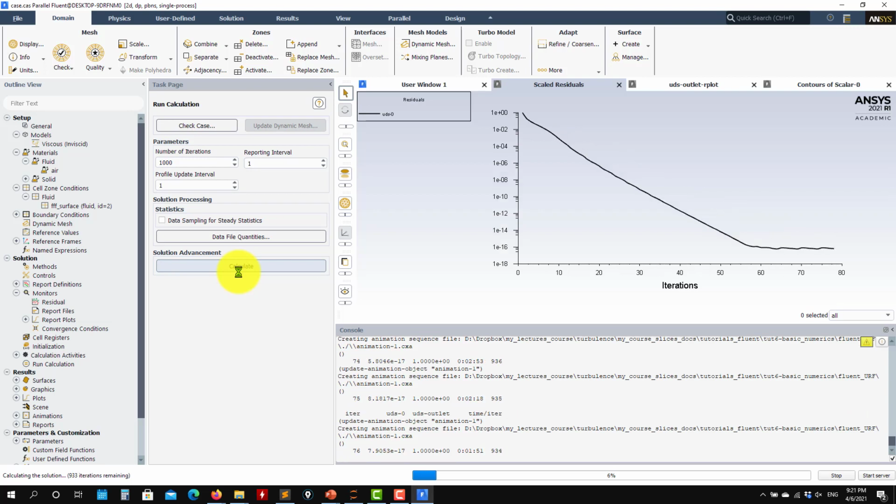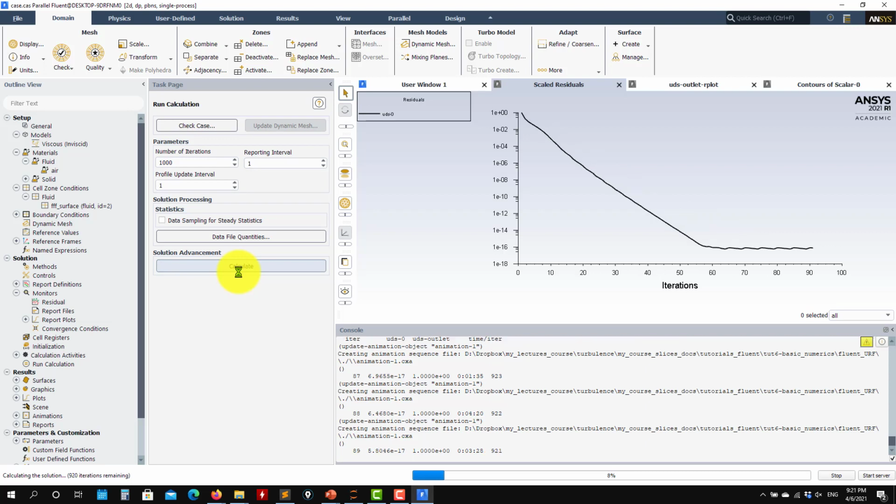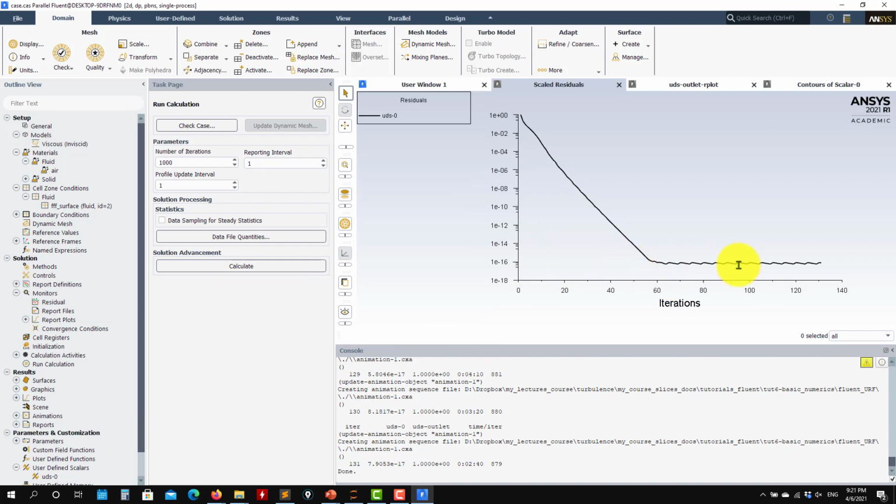And this is something, believe it or not, a lot of people ask me about, worried about why that is happening. Remember that in your computer you have a machine precision. At this point, you have reached machine precision, so you cannot go below this. And this is why I don't like to work in single precision. Remember when you open the solver and you have the options, double precision. Double precision, you can have up to 17 significant digits, no decimal point.